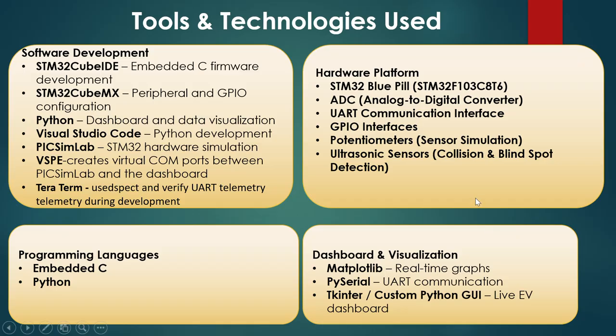Coming to the tools and technologies, for software development, I used STM32CubeIDE for firmware development. I used the STM32 Blue Pill microcontroller, STM32F103C8T6, for the development, and a Python dashboard for data visualization.